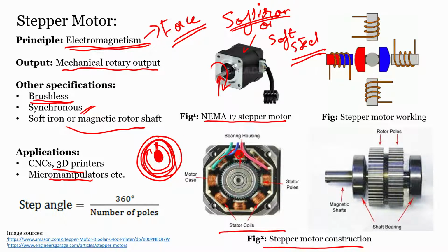But in a stepper motor, it happens in steps. Like this is the shaft, okay, and this was the line. It will rotate and come over here first, then here, then here, then here, then here, and here, and it completes a rotation. Though I showed it like 8 different motions, it's actually very continuous in the sense that once we give the signal for rotating it, it will rotate in steps, but the steps will be close enough that we will not feel like it is going step by step, but it will be continuous. But this is how it works, okay.